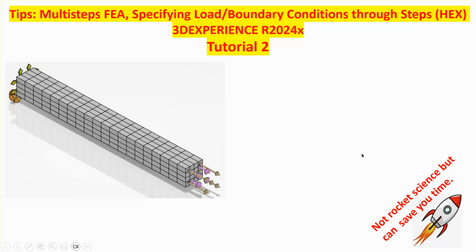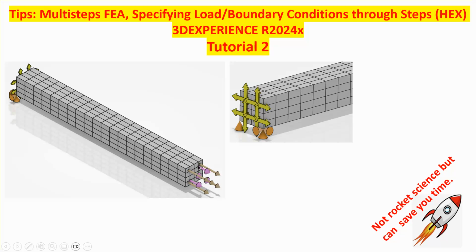Now, because the ideas can be discussed for any type of element, I'm going to use the brick element. I'm going to take a very simple axially loaded member, as shown here. Because it's axially loaded, I don't want to clamp the left side because there will be stress concentration here when you pull this thing or push it in. So I apply a minimum number of constraints here so that it's not a clamp, but it still allows us to run the problem.